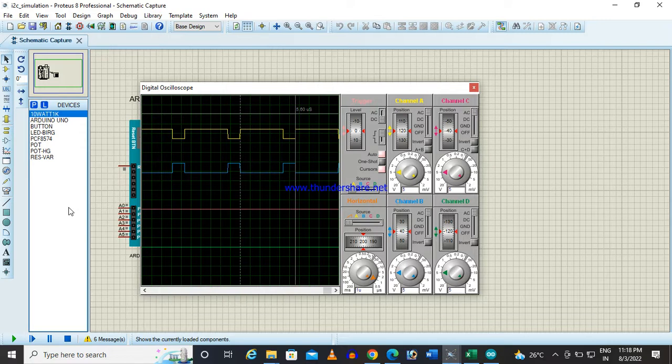Here one thing we understood: if we generate PWM of higher frequency, then the resolution will come down, and vice versa. If you want high resolution PWM, we definitely have to sacrifice the switching frequency. They are inversely proportional. So for a microcontroller, the PWM frequency and the resolution are inversely proportional. Okay, I hope all have understood the concept.